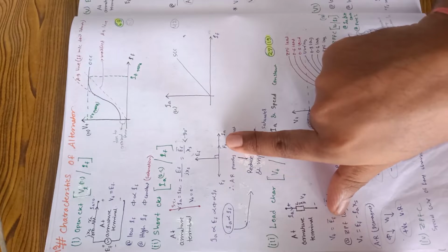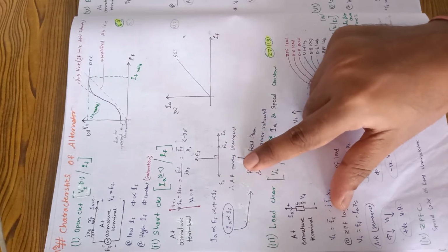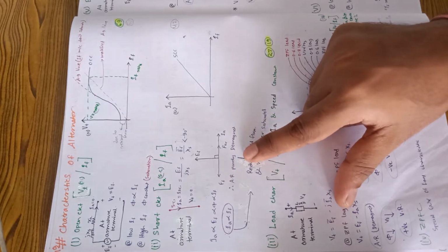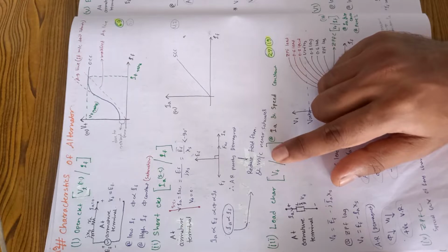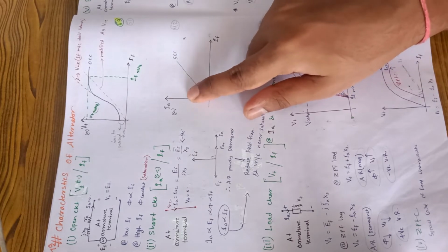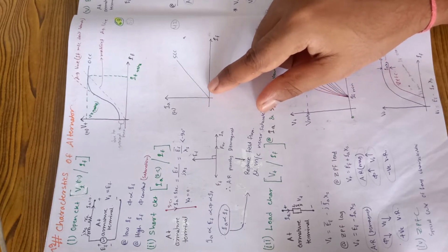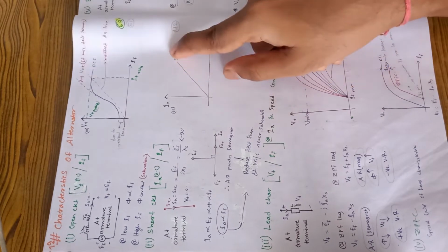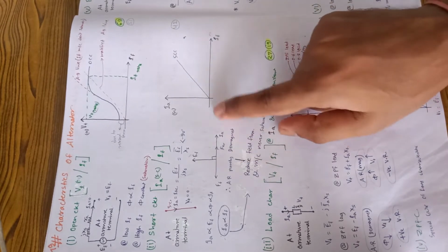In case of purely lagging armature current in a generator, we know very well that the armature reaction will be purely demagnetizing. If it is purely demagnetizing, then it reduces the field flux, and the machine will never get saturated. If we keep on increasing If, Ia will also increase, armature reaction will also increase, and then phi will decrease. The machine will never get saturated, so it is linear in nature. So the short circuit characteristic is linear in nature. Here we can say easily.